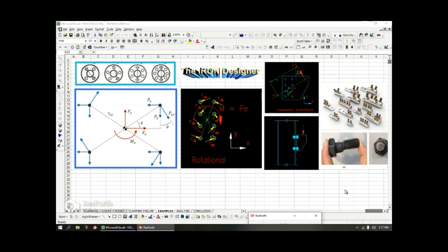If you look at to the right, the diagram, the geometric definitions, you can see in that case the load is coming in perpendicular to one of the bolt centers and is not passing through the centroid. So that would have to be analyzed differently. So you've got the center of inertia, IC, and you've got the centroid or the center of gravity, CG, and you see there's an angle of the force load P acting through the inertia centroid.